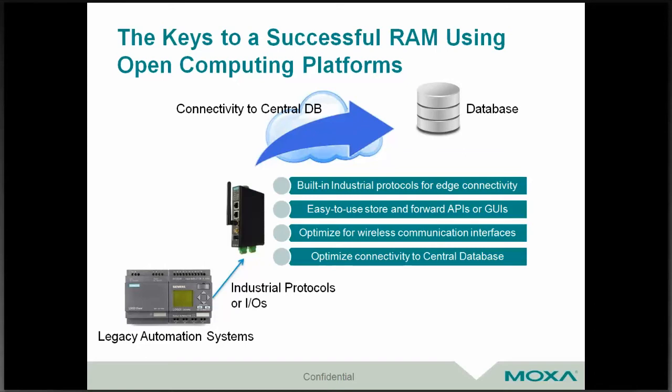Third very important point to do the migration will be the computer itself needs to have a wireless communication optimized for long-haul communications. Moxa, for example, we have products that can have Wi-Fi inside, can have 4G LTE inside, but having all those communication boards inside the computer does not mean you will have a successful long-haul communication because there are simply too many bits and bytes you have to pay attention to when you want to have a successful 4G LTE connectivity.